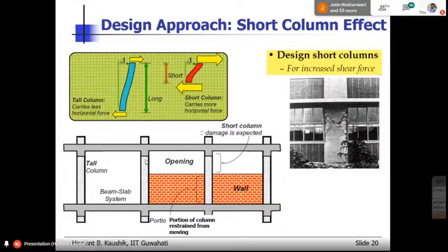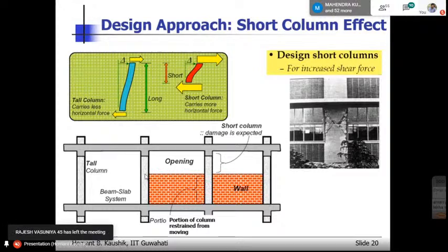For them also people have come up with various techniques, where they start modeling the hinge from this point to this point. There are people who want to do research on anything and everything, but the best option here is to avoid the failure, not to model the failure. Even if you model this using the strut, you're not avoiding the failure, right? You're just finding out how to model the behavior. Our job is to avoid it, to prevent it.